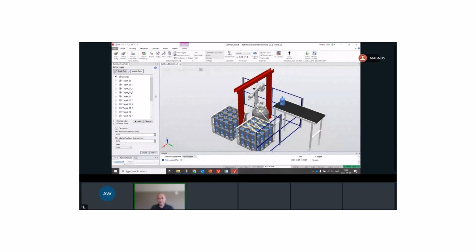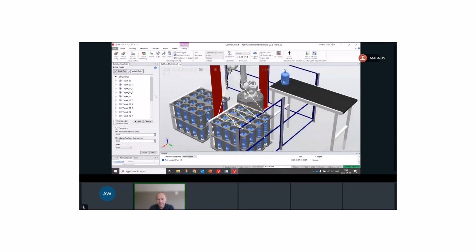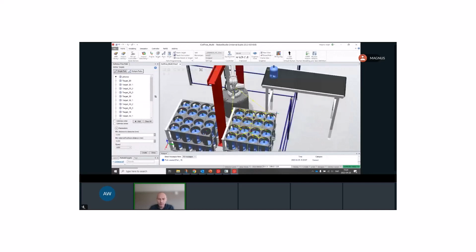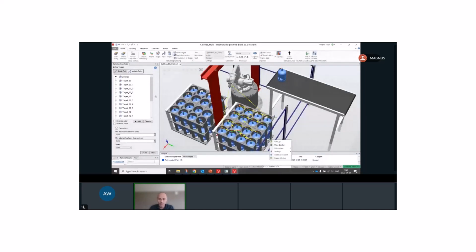And the system creates the path for you in the way that we have selected and ordered the targets. But you can already see just by looking at it, it's far away maybe from the most optimal way. We go here, etc. and so forth. But instead, why not we let the system optimize the path, the routing? If you have no dependency really that you have to go there before the other one, let's calculate the shortest path for you so you can optimize the order.